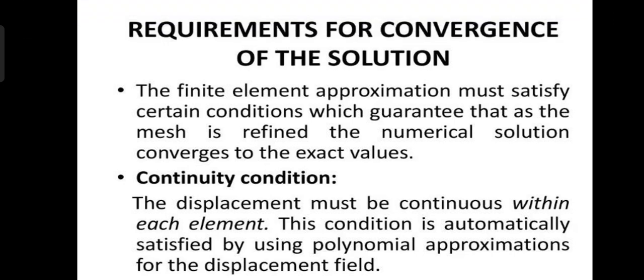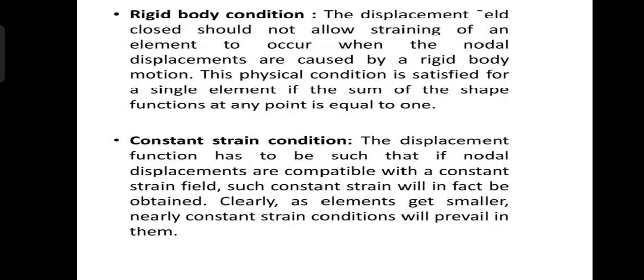Coming to requirements for convergence of the solution, the finite element approximation must satisfy certain conditions which guarantee that as the mesh is refined, the numerical solution converges to exact values. The continuity condition: the displacement must be continuous within each element. This condition is automatically satisfied by using polynomial approximations for the displacement field.